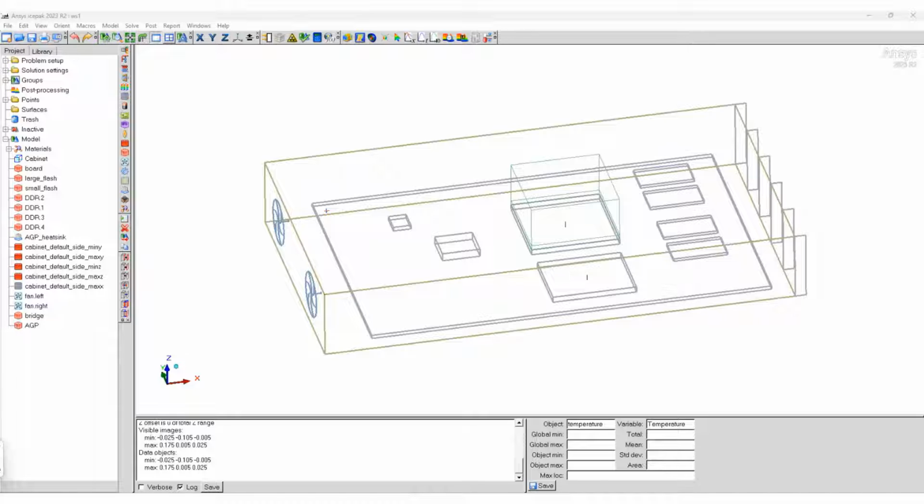The objective of this video is to try and understand the solution workflow in Icepak Classic. We will modify simple solver settings and create different monitor points, check solution convergence, and verify mass and energy conservation, and also post-process the solution. Look at the solution using a cut plane solution at the faces, and also look at various plots.